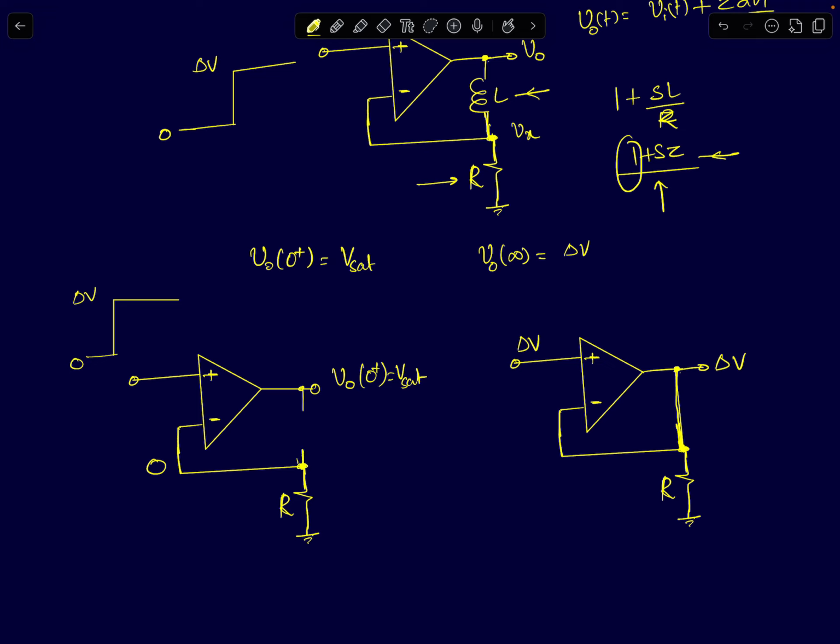Saying it is an open circuit is equivalent to saying that the current through an inductor cannot change instantaneously, or the incremental impedance of the inductance will be infinity, right? A step input signal at t equal to 0 can be seen as a sinusoid of infinite frequency. And the impedance of your inductance is what? The magnitude of the impedance is omega times L. So it blows up to infinity. That's why I've written it as open here. So the inductor will act like an open circuit.